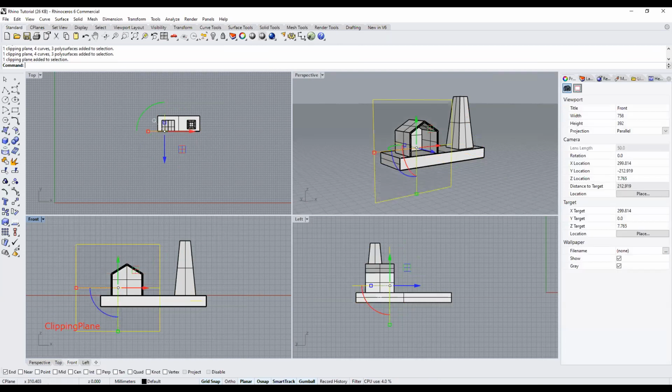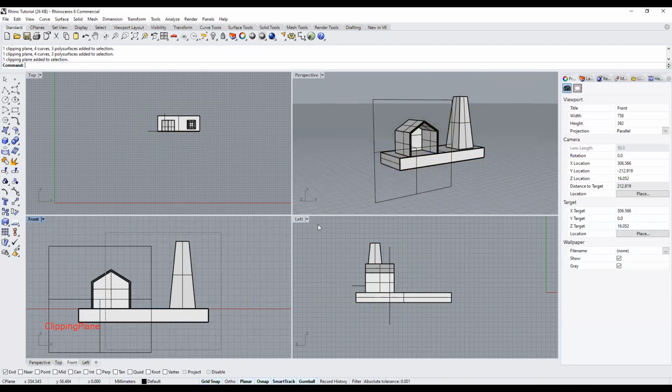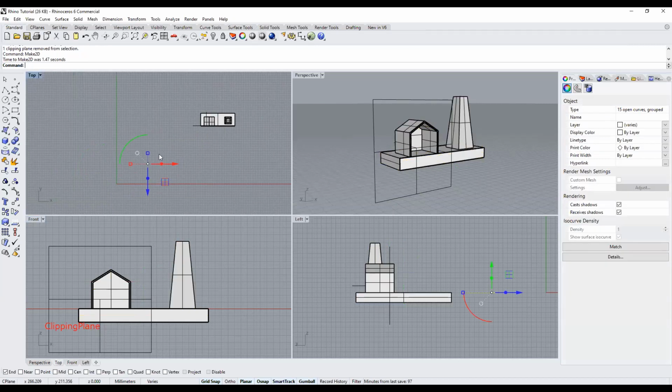Yeah, select everything, deselect using control, make 2D. And clipping plane in sections is ticked. So that will mean that anything that's cut by the clipping plane will show up in an outline. And because clipping plane is shown is ticked on the top view, which is why you probably don't see a line right now. But if you drag this back, you'll see this.